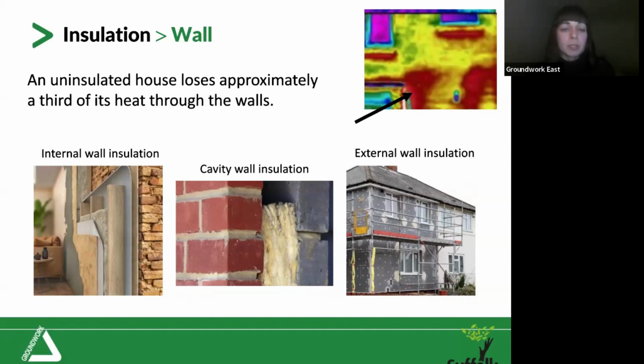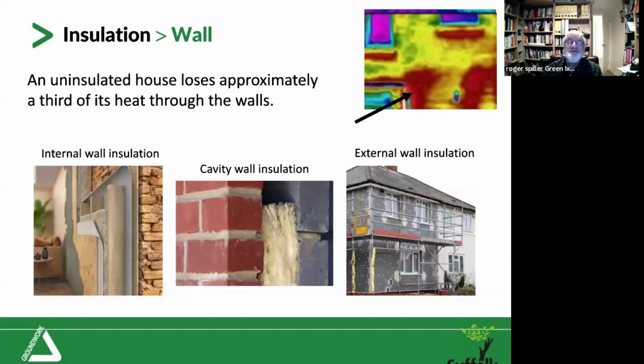Spray insulation is difficult because in some situations it's worked really well for people. There's been a lot in the news about spray insulation, about, like Roger was saying, how damaging it can be if it's applied incorrectly. It creates bridges within the building and the structure, so that something which would normally be wet but ventilated and isn't a problem suddenly becomes part of the structure, and you can't get rid of the damp, and then it creeps.